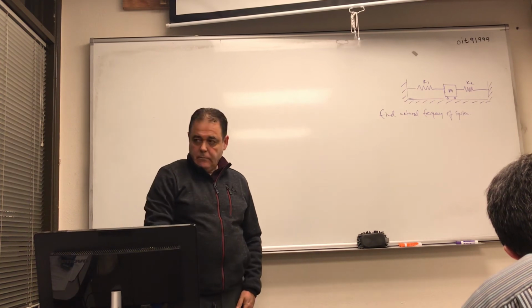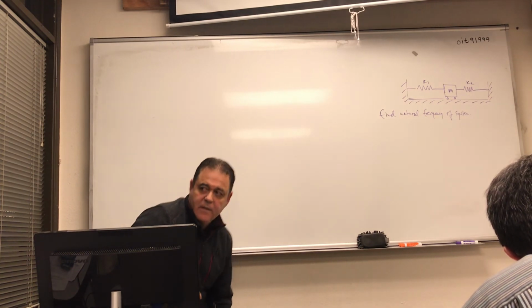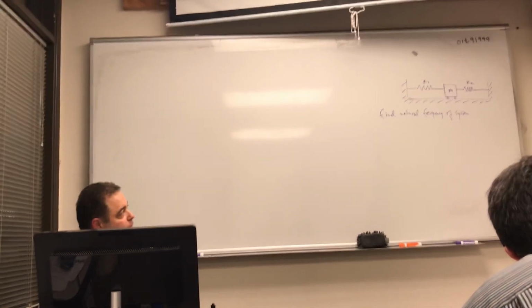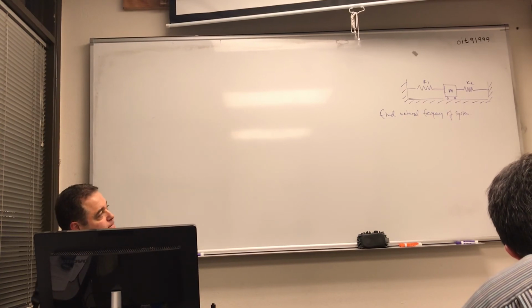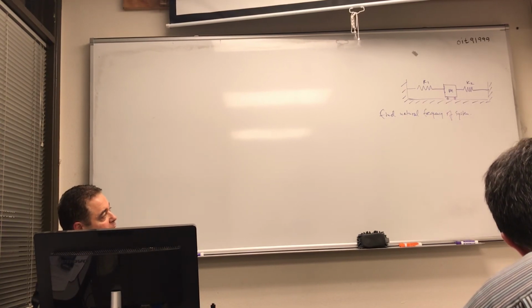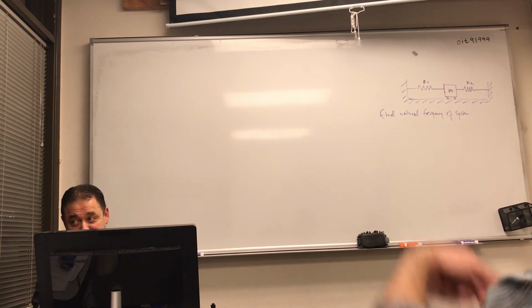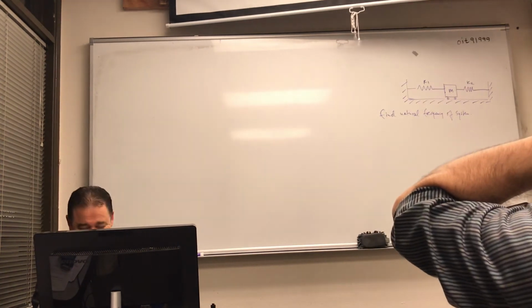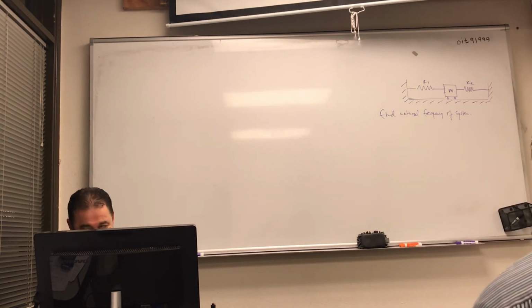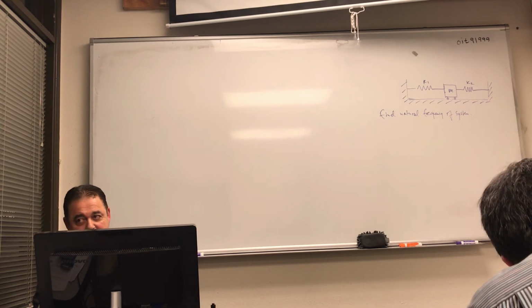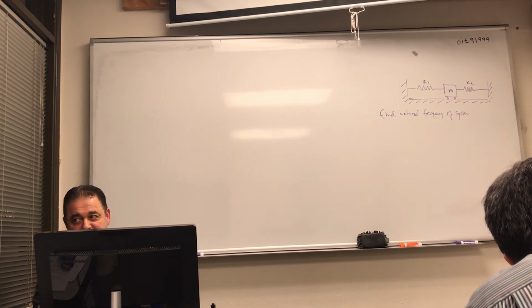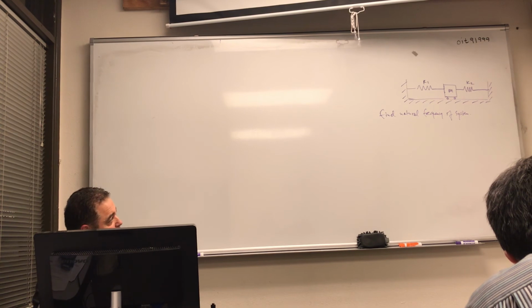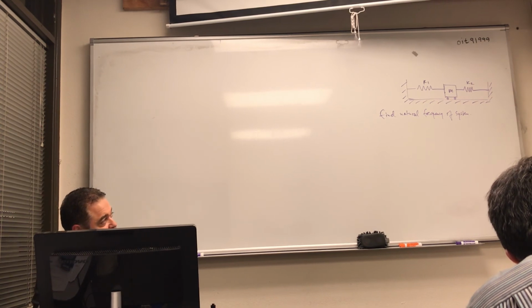That one's a pretty quick one. That one, in series, because it would be root K over M, and you just take the K equivalent, and that would be it. Wait, say that again? You just do root K over M, that would be the equivalent? Well, he said the natural frequency, which is root K over M. But you'd have to find K equivalent in series, so it's K1 plus K2. Is that right?